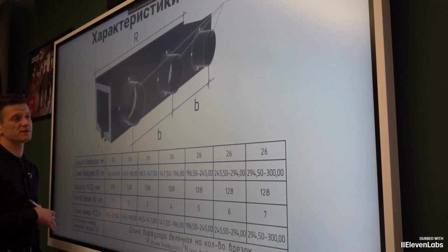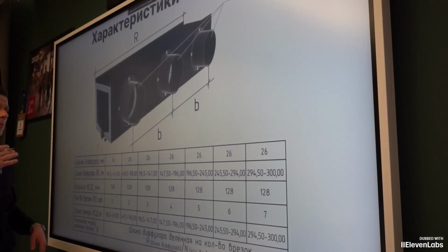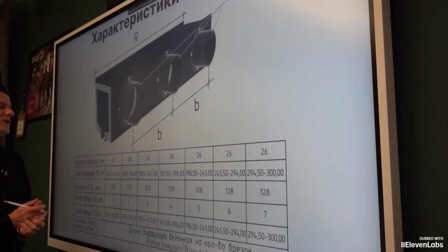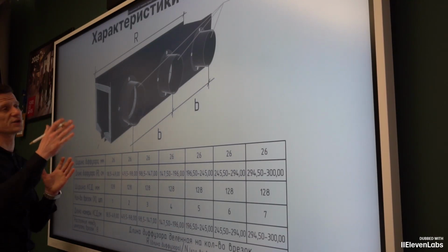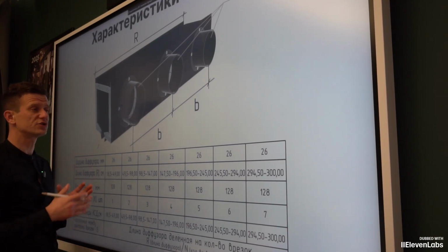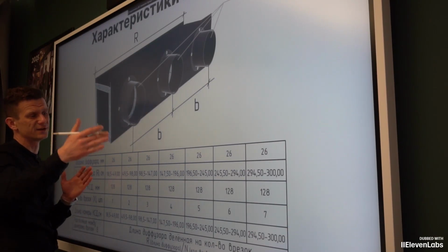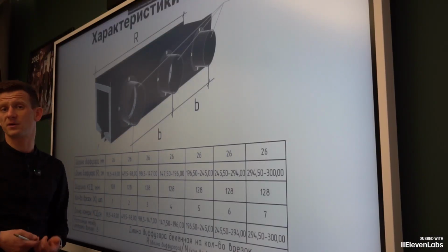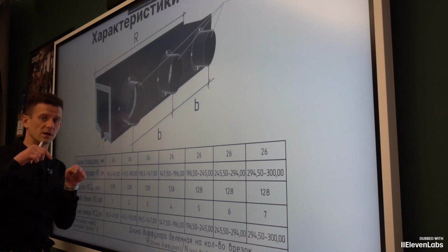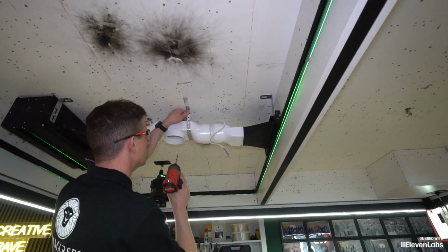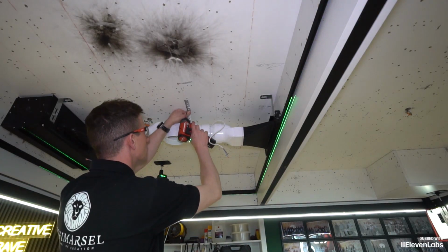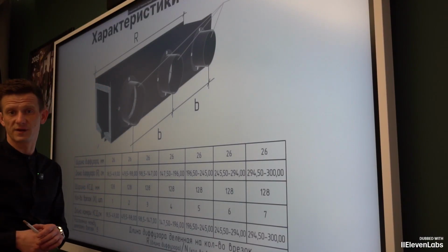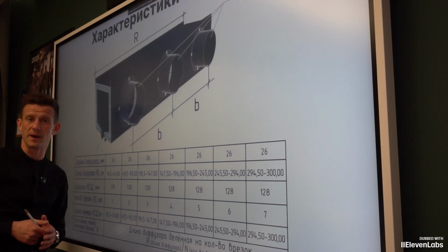What I would like to add about the input couplings is that after analyzing the market for similar solutions, we have come to the opinion that the number of input couplings should be calculated based on the length of the diffuser. A table will be presented below and it will be available in the AIRPIPE catalog, which you can download via the link in the description of this video. During the design stage of the ventilation, you can immediately determine the number of these inputs into AIRPIPE.